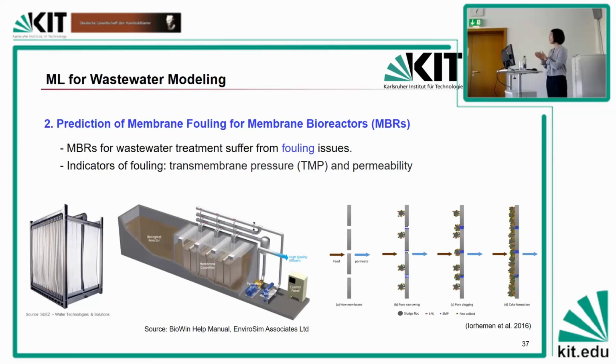So this means every once in a while, you need to backwash the membrane to clean the membrane using chemicals, or you even need to shut down a unit and then clean it manually. But the more frequently that you clean it, the more cost that would bring. So they want to predict when fouling is going to happen. So that's what we did.